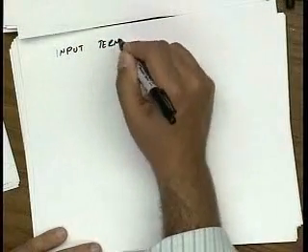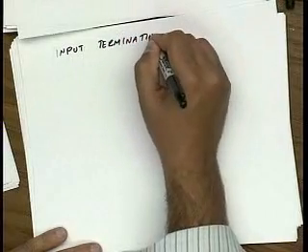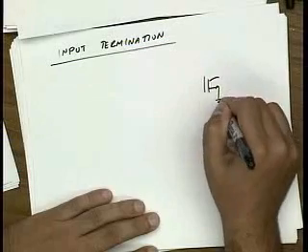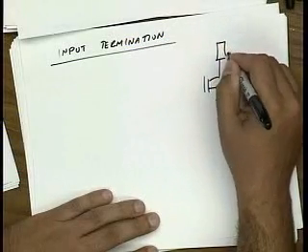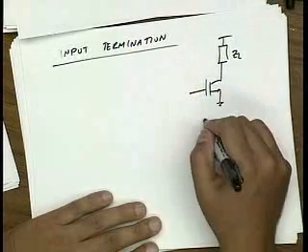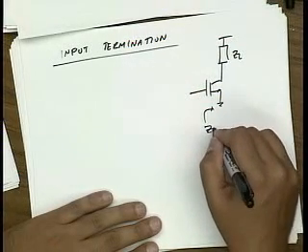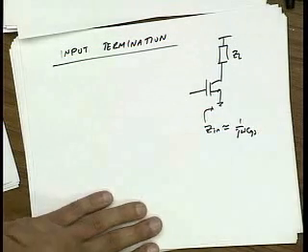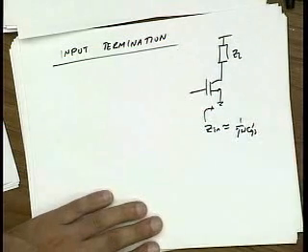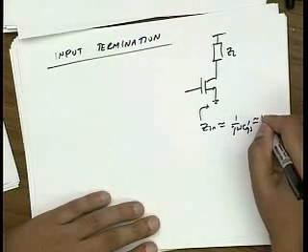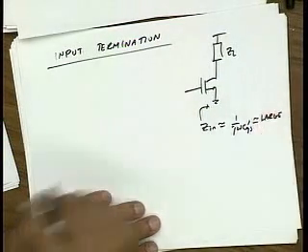So what are the simplest ways of matching an LNA? And actually quite common is just an input termination. In other words, if I take this common source amplifier that has very good noise performance, as we've already seen, at low frequencies or at moderate frequencies, Zin is 1 over j omega CGS, or effective CGS because of the Miller effect, which is basically large if the device is not too big.